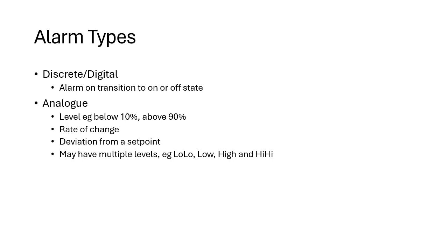We could also have rate of change alarms. Maybe the tank is filling too fast or emptying too fast, so that could generate a rate of change alarm.